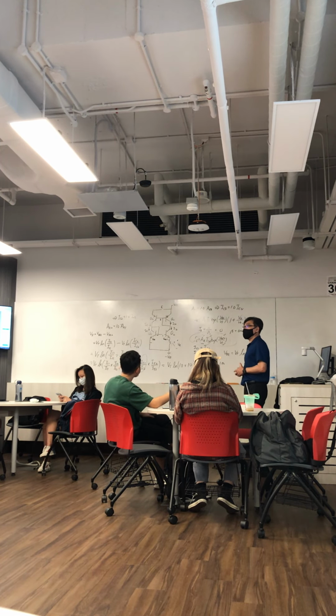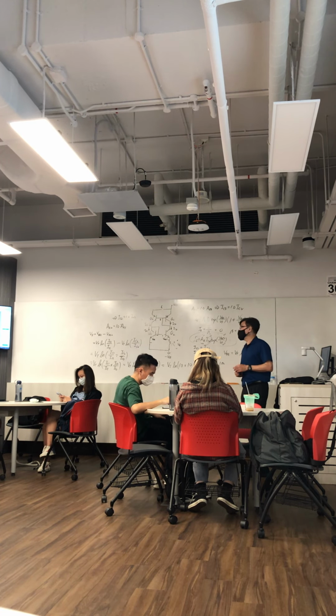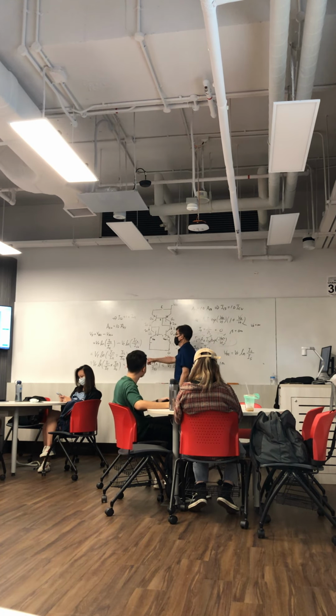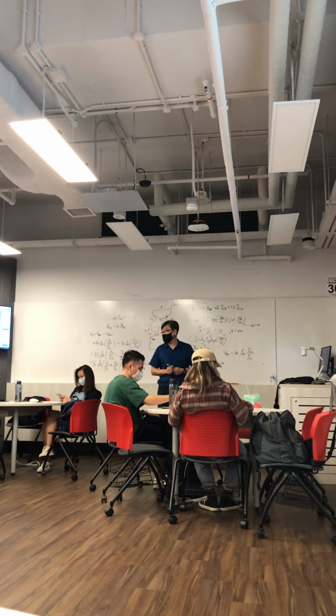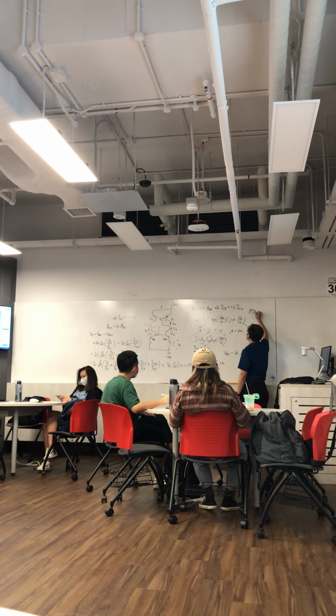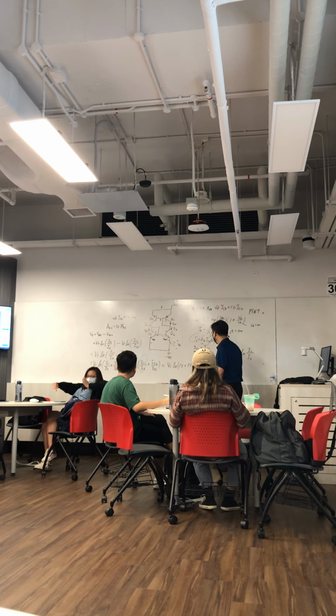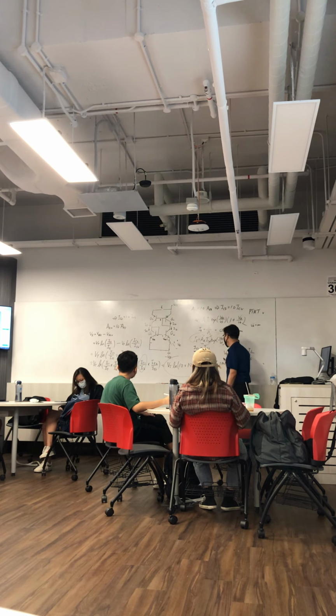Okay, now once you get this, I want to get to the point why this voltage here has a special name: proportional to absolute temperature, PTAT. Why? Because you notice this expression. This part is constant.